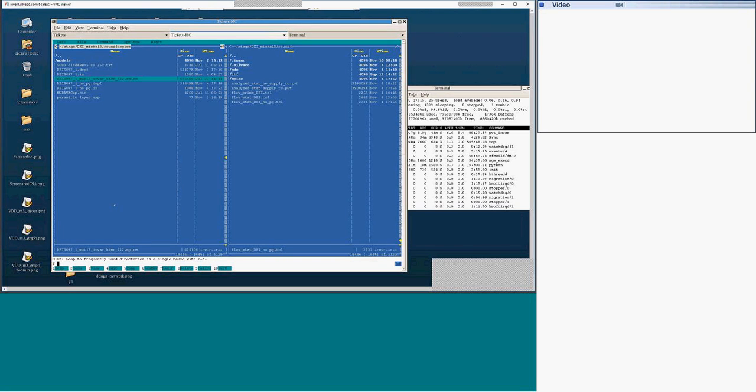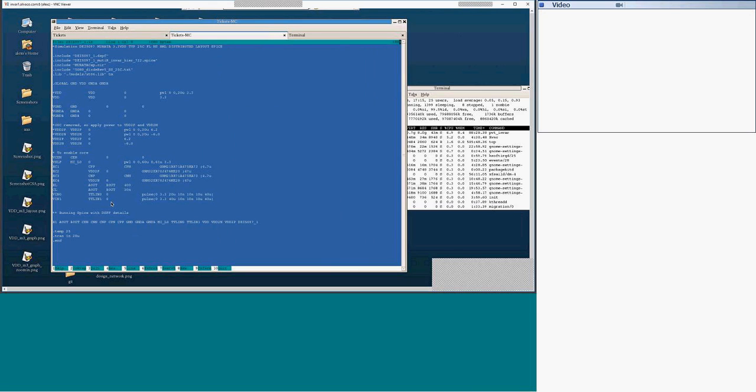So I have what I have. In your original SPICE netlist, what we have, and what we really need to have. We have the extracted DSPF. You can see it on line 3. You may have some libraries and supplementary subcircuits included.